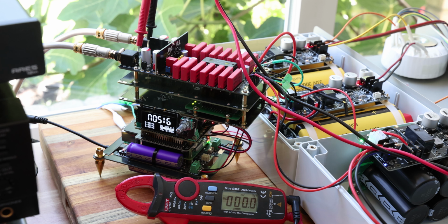And from time to time maybe just check it out. But if you do have an amplifier that seems to react badly to DC, the ultimate solution is to put a capacitor in between them. Not my preferred way, but it could be your only way. I've rarely seen an amplifier that really malfunctions in those kinds of conditions. But nevertheless, try it first on your own amplifier, and try it on a cheap amplifier first to make sure the first time it's running.